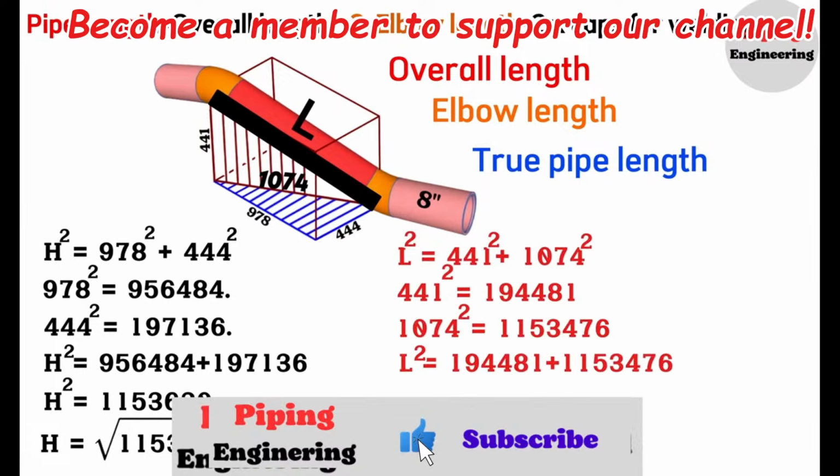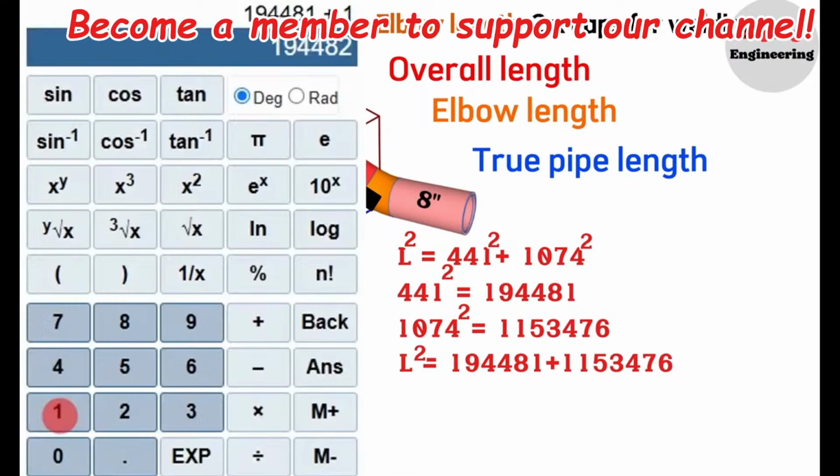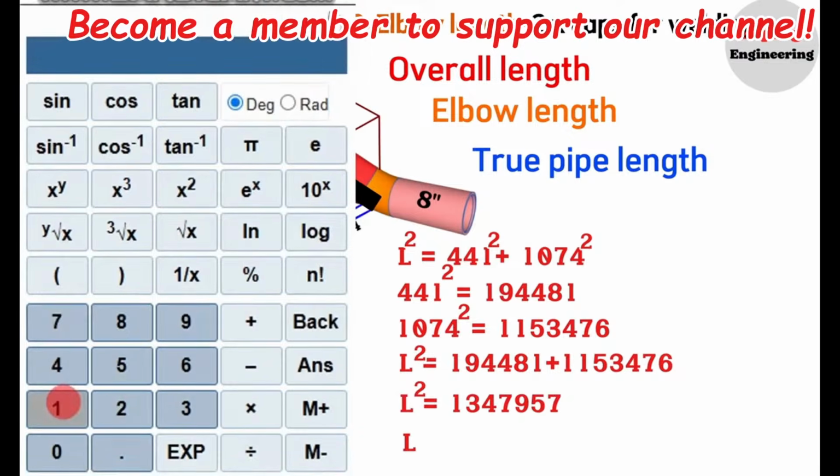194,481 plus 1,153,476. Using the calculator again, 194,481 plus 1,153,476 will equal 1,347,957. So, we find that L squared equals 1,347,957. Again, using a calculator, L will equal the square root of 1,347,957, which is approximately 1161. The hypotenuse of the vertical right triangle also serves as the overall length, or the center-to-center distance between the two elbows. So, after our calculation, we found that the overall length or the center-to-center distance between the two elbows is 1161 mm.